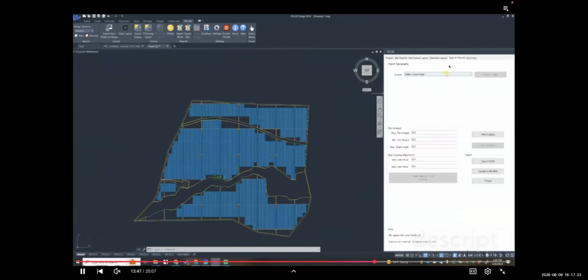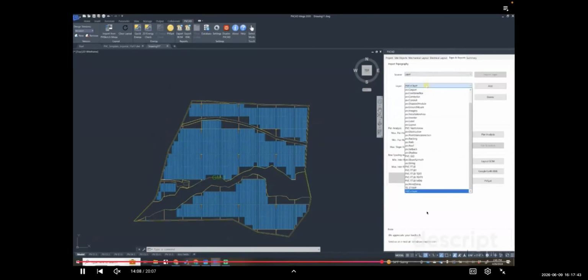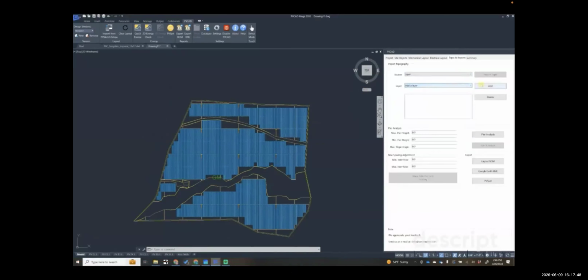So if you have a topo file in CAD with contours, you can upload that and use that to do your topography analysis. Or we also have Google elevation services. So that will basically create a topo analysis and give you, I'll show you how, you can look at in Google Earth as well, like the Google Earth KML file, and see the actual design and which are the hilly areas, so you can complete your pier schedules as well.